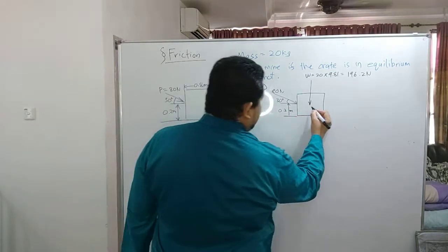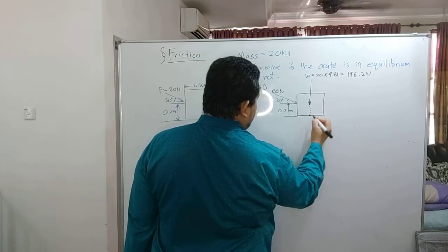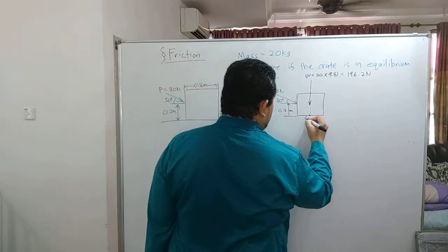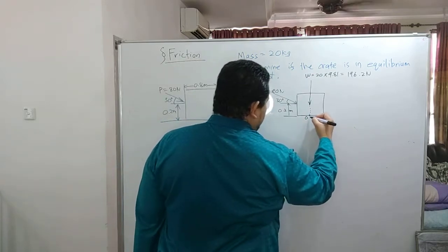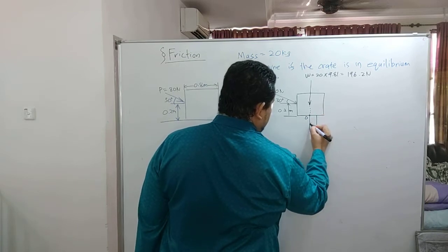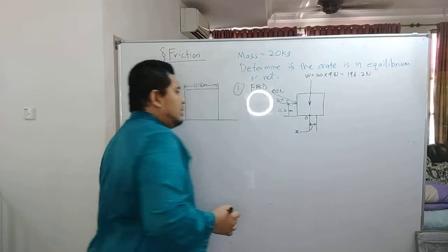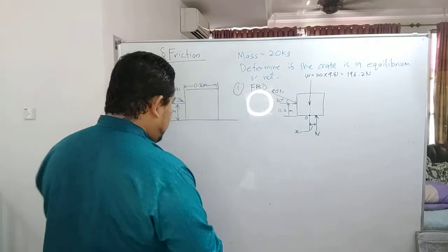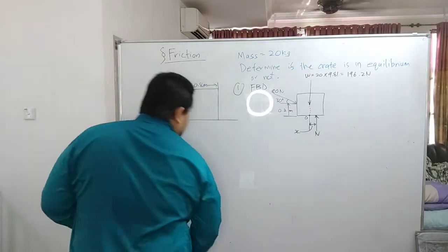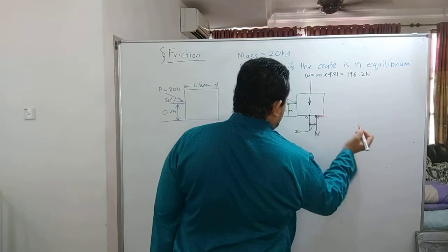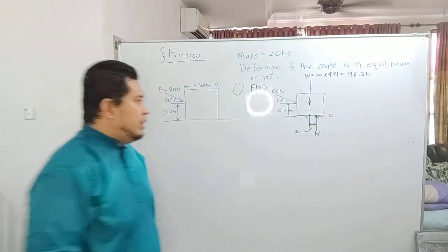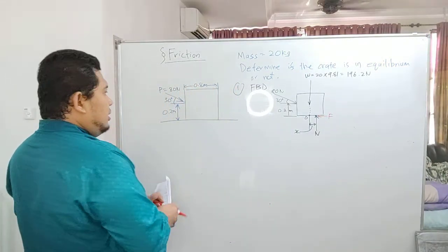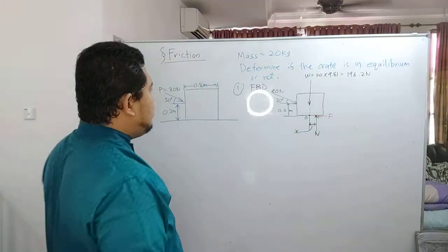And then extrapolate this line over here along the center of gravity. Put O here. Then you can have X over here. Okay, and then here should be the normal force N, and then don't forget lastly the friction force F over here. You do not put whether it is Fs or not, just put F first. So this one is the free body diagram for the friction problem.